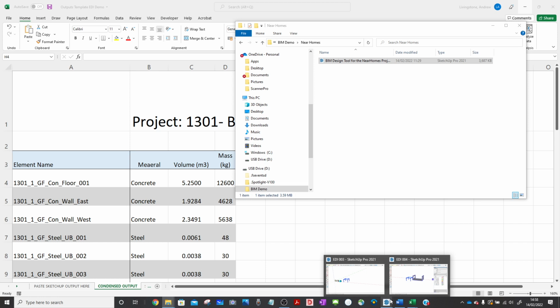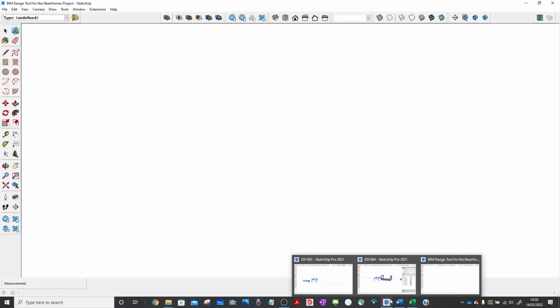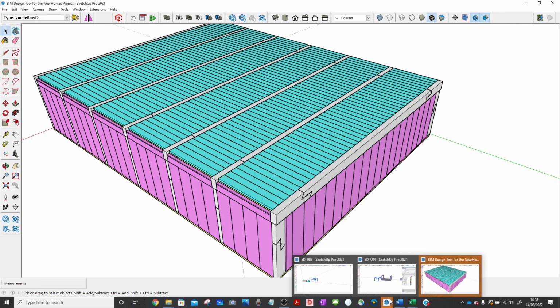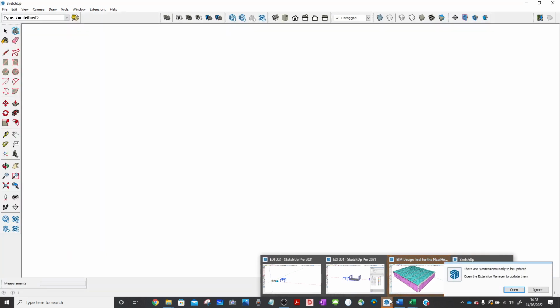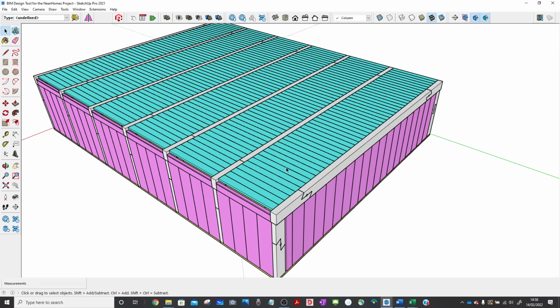If it was indoors, it could either be what's called a low-risk scenario. A low-risk scenario would be a shopping mall where you've just got a door into the unit. A high-risk scenario would be you've got a big industrial unit with a roller shutter door, and somebody may choose to open the roller shutter door from time to time. That means the air pressure is different. Okay? So, if you've got a building inside, the air pressure changes, then what you've then got is a horizontal load action on the building.